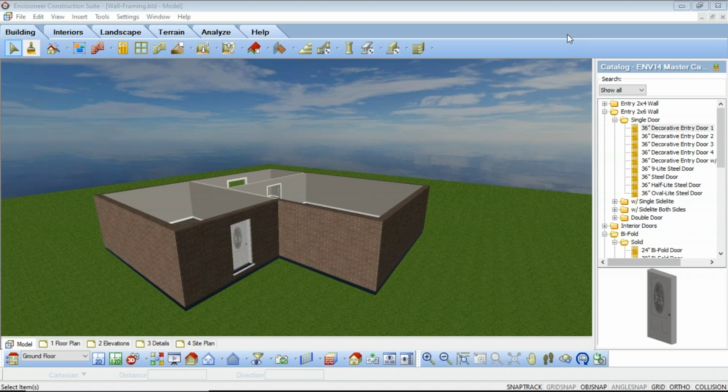Wall framing settings. Each location in your building locations dialog has a set of framing options that determine how walls, openings, and intersections on that location will be framed. Location framing options include a span table selection for walls, an infill configuration, a framing rule, and an intersection reference table. We're going to look at the available wall framing settings.